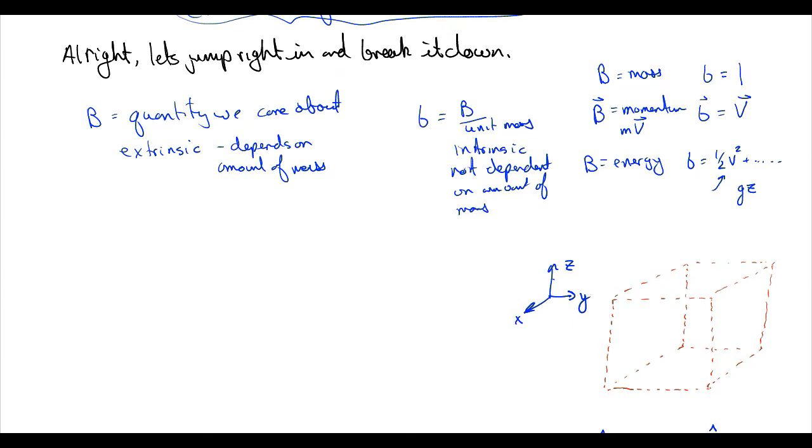But what we're going to do is take the material derivative. Remember that from the last lecture. dt of some system quantity of B. And it turns out this is equal to d dt, the change in time, of an integral over our control volume of our density times our lowercase b, integrated over the volume of our control volume.